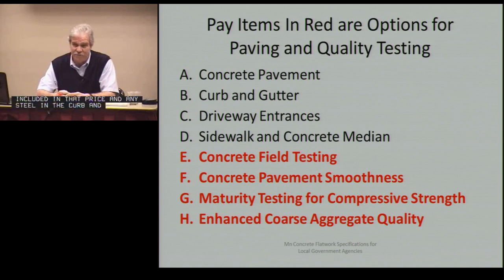Driveway entrances, the same thing. You'd have probably 6-inch and 8-inch driveway entrances, so you'd have 2 different bid items. The DOT generally puts in 8-inch driveways for commercial driveways and 6-inch for residentials. And then sidewalk and concrete, medium concrete for your sidewalk or your medium concrete.